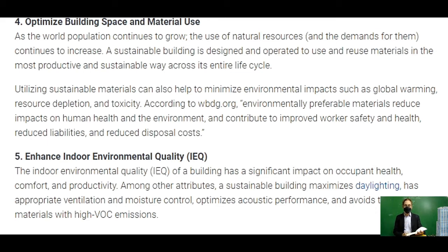Number 5, enhance indoor environmental quality, IEQ. The indoor environmental quality, the IEQ of a building has a significant impact on the occupant health, comfort, and productivity. Among other attributes, a sustainable building maximizes daylighting, has appropriate ventilation and moisture control, optimizes acoustic performance, and avoids the use of materials with high VOC emissions.